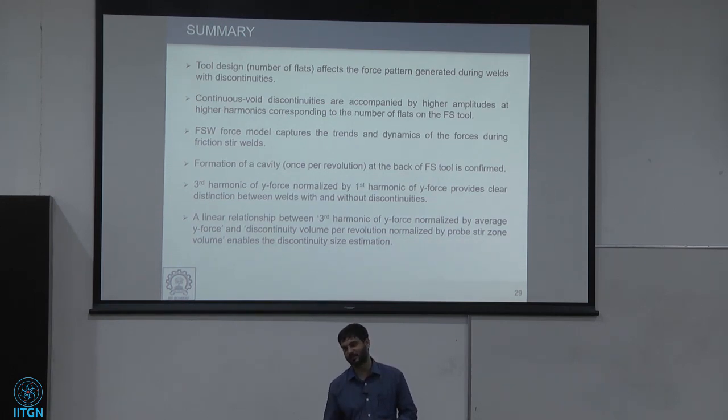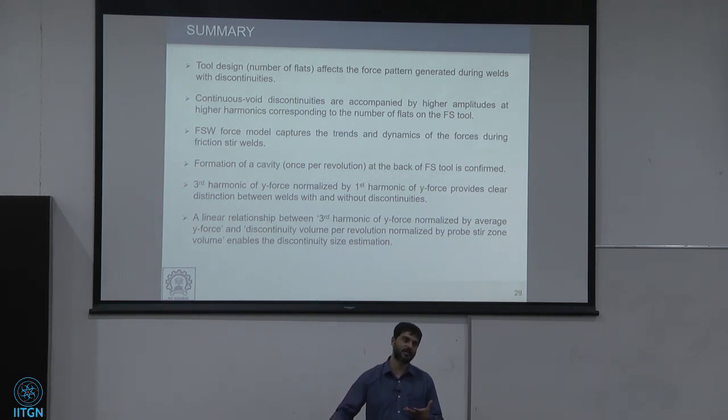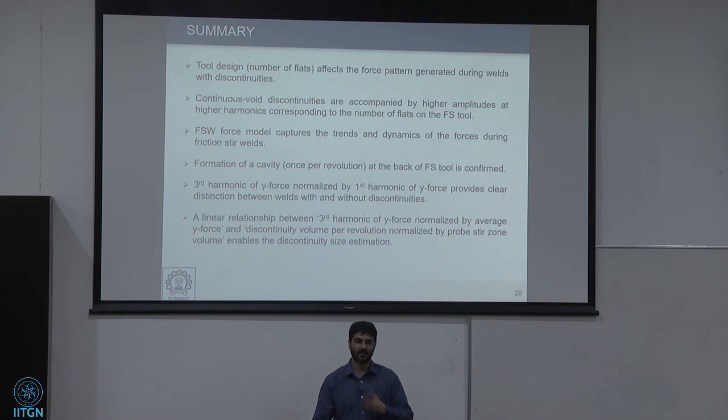Now the additional harmonics which are observed have been exploited in the proposed method. The additional force dynamics is observed at a higher harmonic corresponding to the nth multiple of the tool rotation frequency, where n is the number of flats.